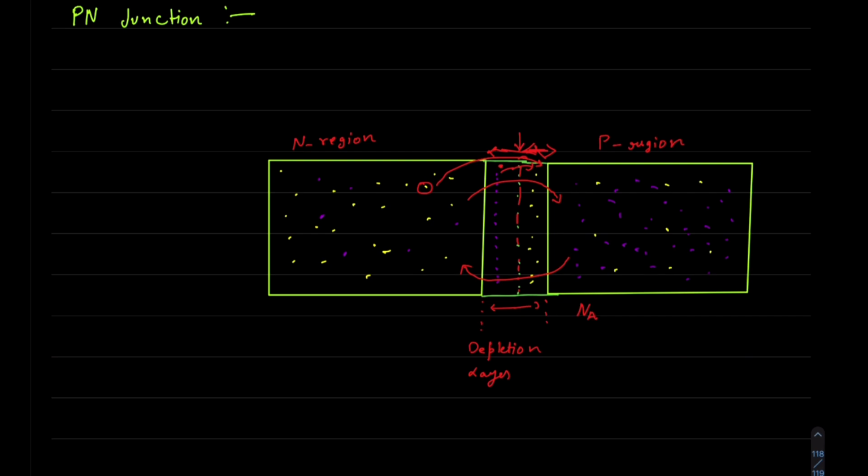So diffusion happened, and after a certain point it reaches equilibrium, but we'll talk about that as well. The width of the p layer and n layer depends on how heavily each side is doped with acceptor density Na and donor density Nd. This process continues back and forth until the number of electrons which have crossed the junction have a large enough electrical charge to repel. So now, lots of electrons have come here. Lots of electrons are now in this place.